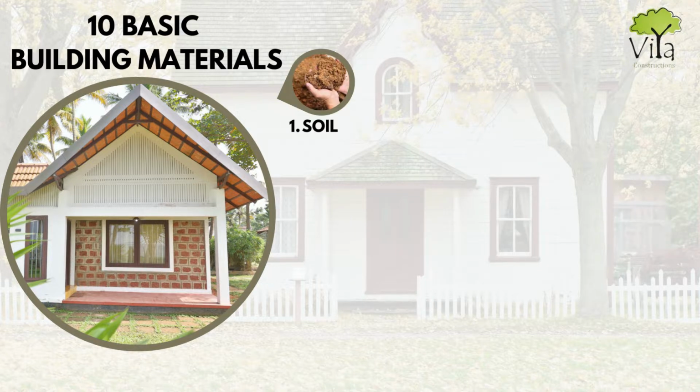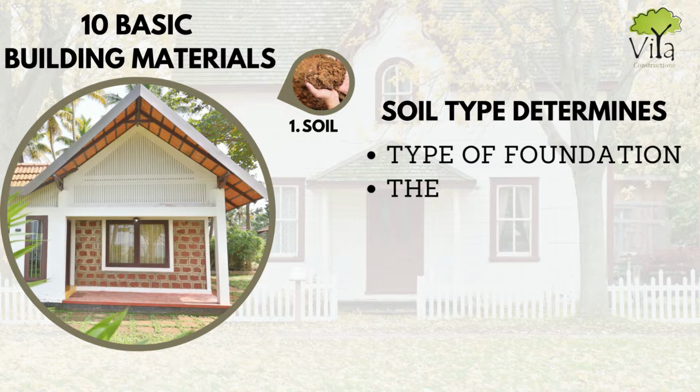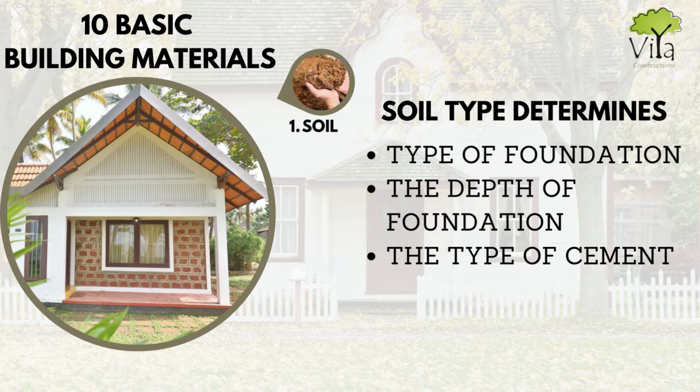Soil. Though soil is not a building material per se, it plays a very important role in construction. Before you start the construction, it is imperative that you test the quality of soil in the plot. The soil test results will help you make key choices like the type of foundation to be used, the depth of the foundation, the type of the cement to be used for construction, etc.